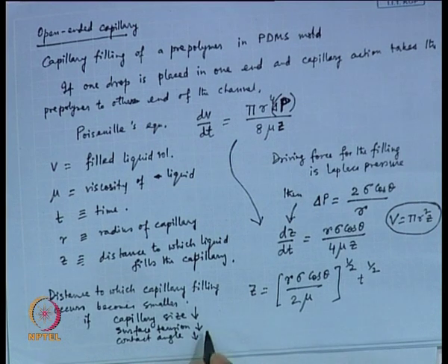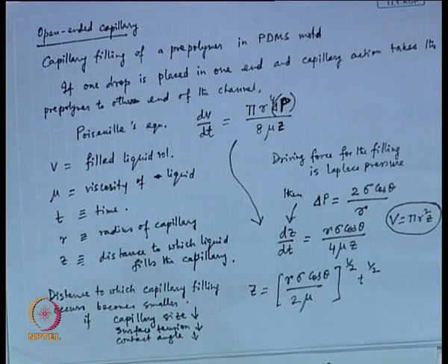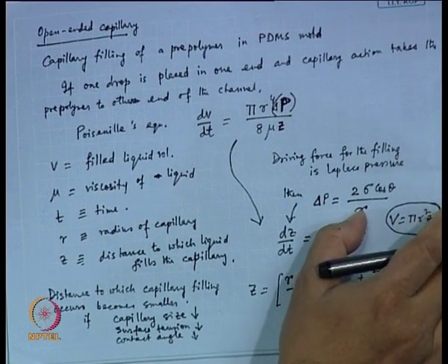So, you want them to be up so that you can have faster filling. Viscosity you probably do not have much control over, because it is the pre-polymer that you have here. Anyway, for viscosity it is inversely related, so that dependence you can see here.